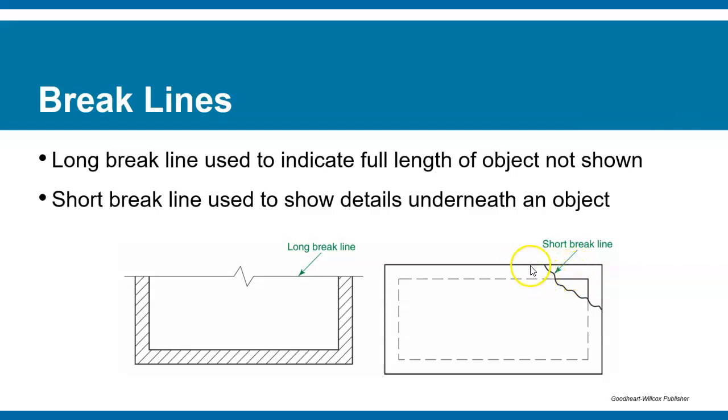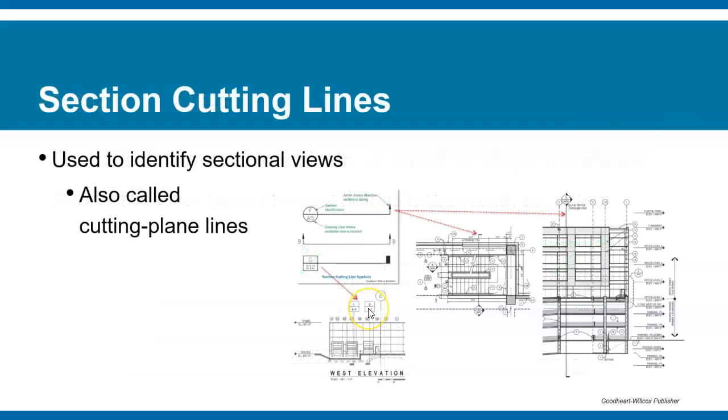The cracker goes to the edge, meets the solid line, whereas the cracker covers the dashed line underneath. But since it's broken, snapped off, the short break line shows you what would have been underneath now is exposed, solid. Okay? So again, that's how you would visualize in your mind.